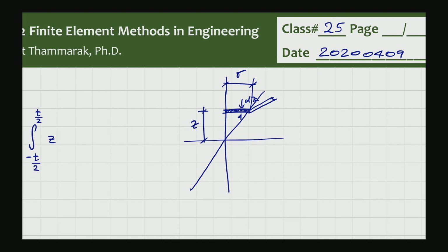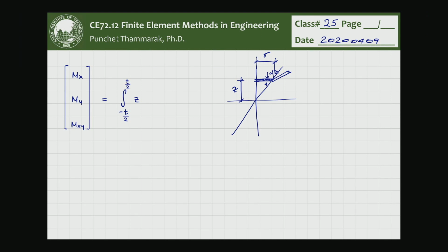So when we analyze, we get the moment per unit length, and then you can provide the corresponding reinforcement to be enough, and so on and so forth. So you have moment arm multiplied by stress multiplied by the thickness, then you get the force per unit length. Force per unit length multiplied by the z, which is the moment arm, you get the moment per unit length.